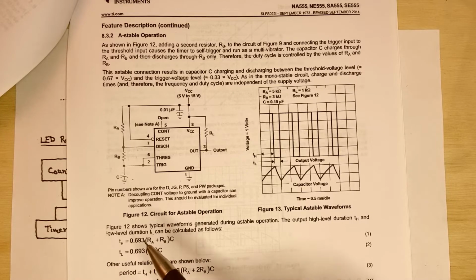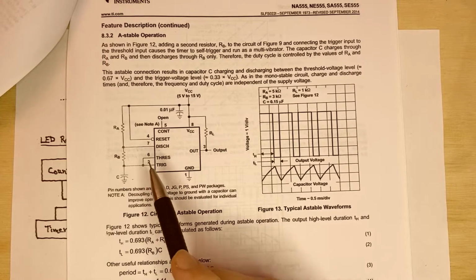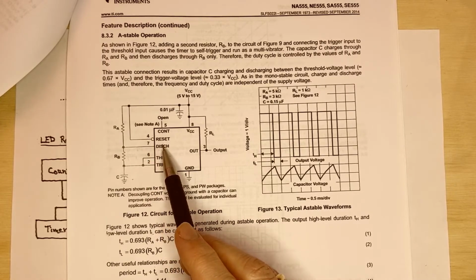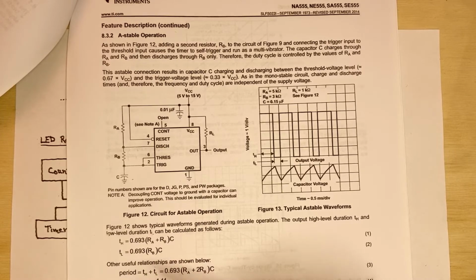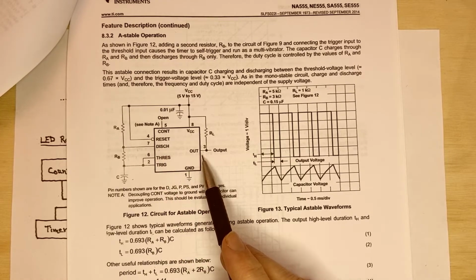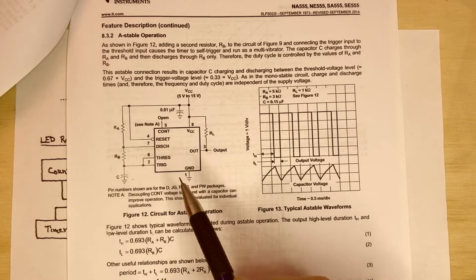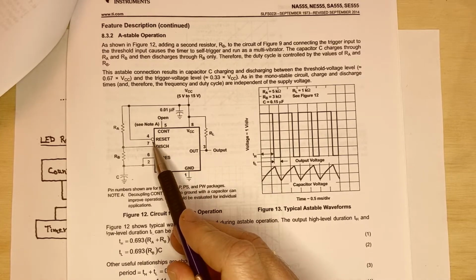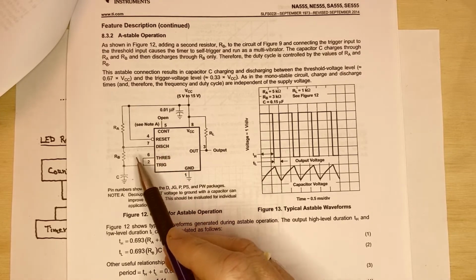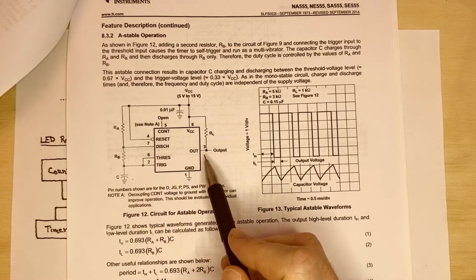And so let's check out the other pins. Pin 5 is left untouched, so you just leave that open. That's easy enough. Pin 4 here is the reset pin, and this is a kind of an override mechanism that once the reset is engaged, the output is pulled low regardless of what the other pins have on their inputs. And anytime on a schematic, if you see a little bubble like this in digital logic, that means that this pin is called active low. So if we want to reset this chip, we need to send a low pulse to the reset, and that will reset the whole chip.